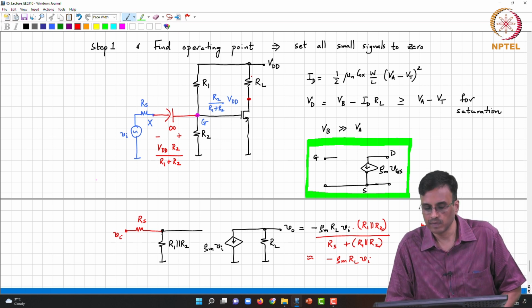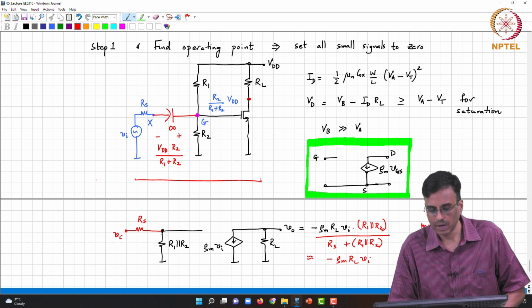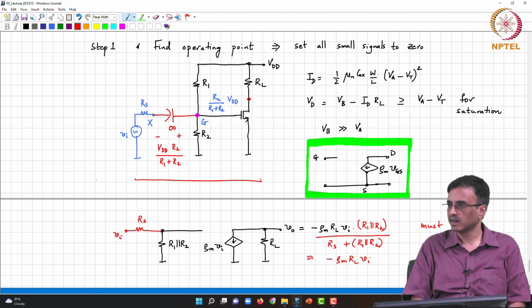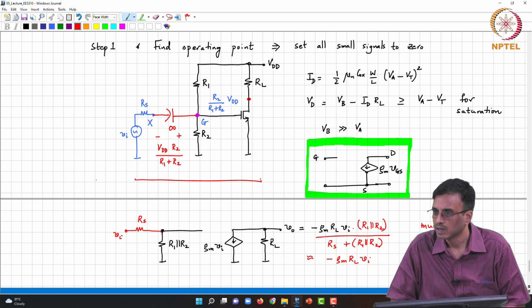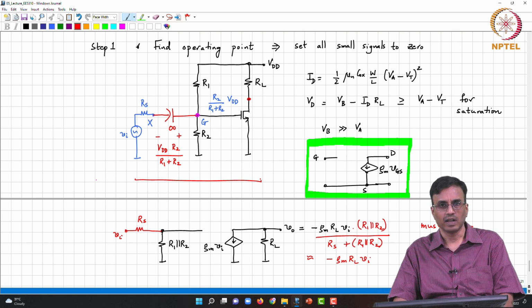And another little problem with the circuit here is the load. What comment can we make about the current through the load? Is it a DC current? Is there a DC current flowing through the load? Yes, okay. So, it turns out that in practice many times it is not permitted to have DC current through the load. An example of such a load is a loudspeaker, because it's a coil around a magnet and so on. You will saturate the magnet if you have DC current flowing through the coil, and therefore, in many cases you are constrained to make sure that the load does not have any DC current flowing through it, okay.